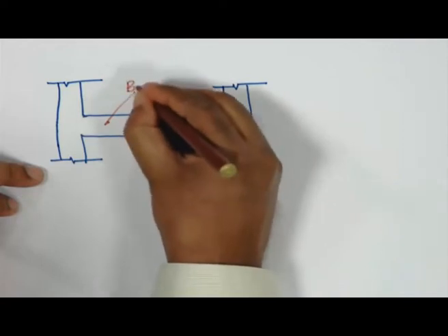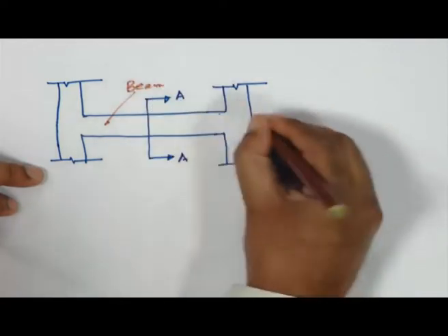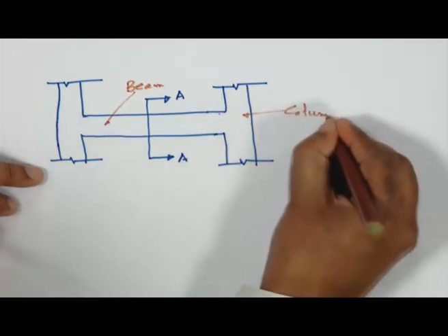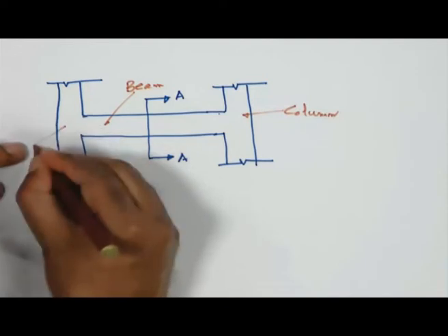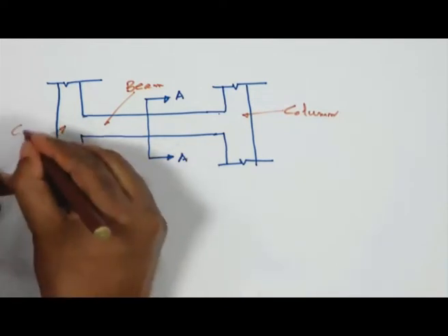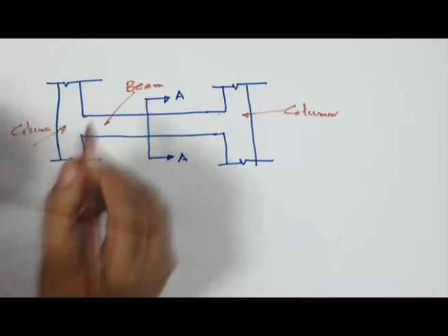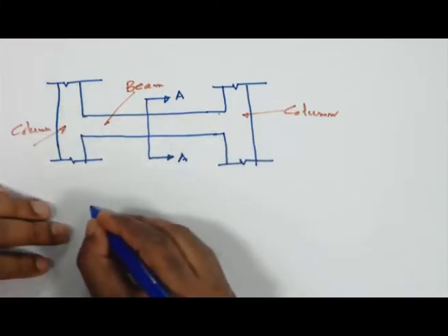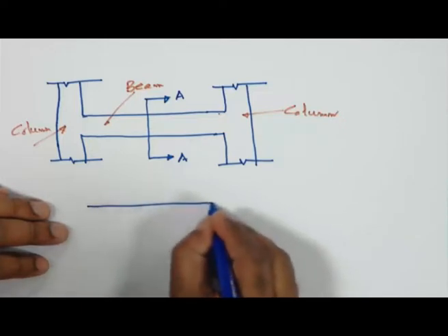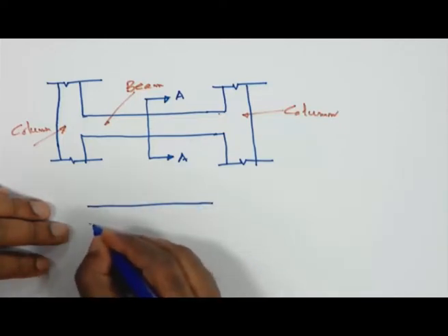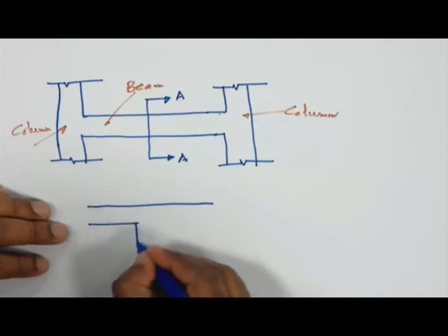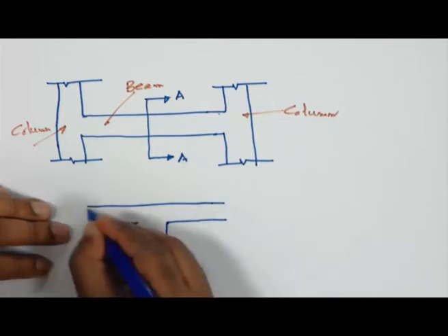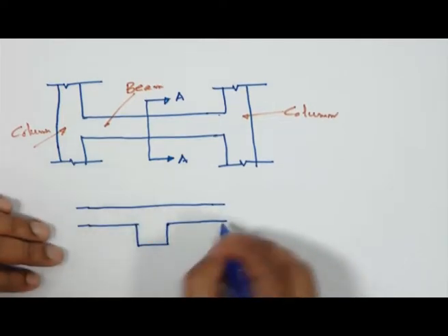So here this is the beam, and somewhere here, let us consider D. It will be clear because that means there is a force C at the top, and this C and T have a lever arm Z. So C times Z or T times Z is the moment, in terms of C or T. You can consider this as a moment.